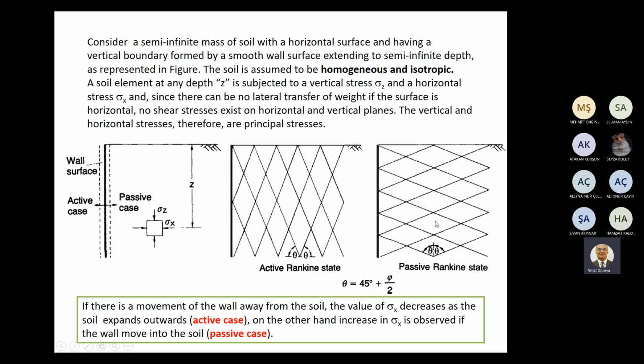In passive case, because the maximum stress will be along x direction, the principal stress trajectory will be changed, overturned 90 degrees, and failure planes will be as shown in this figure.